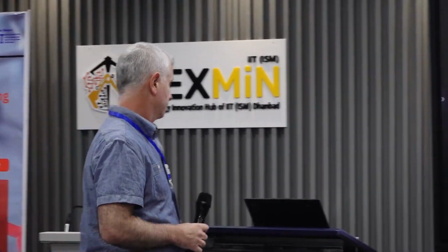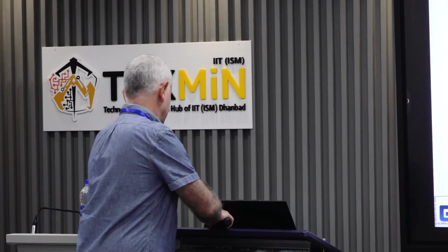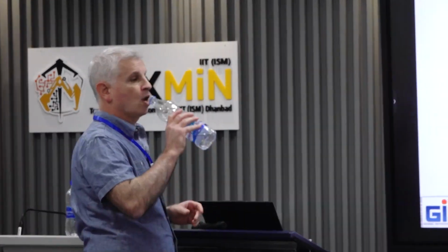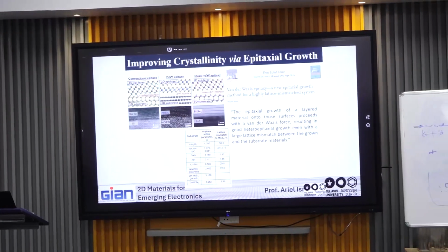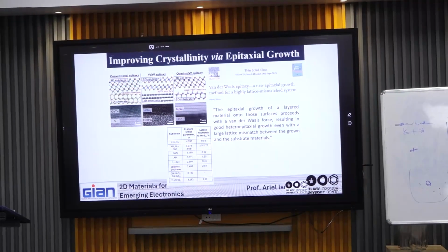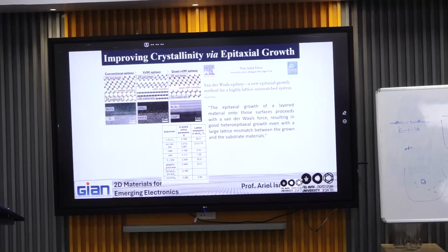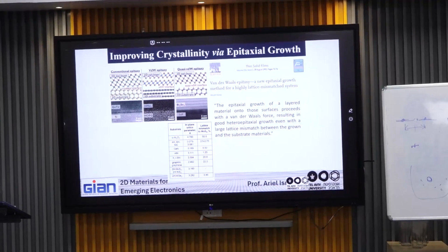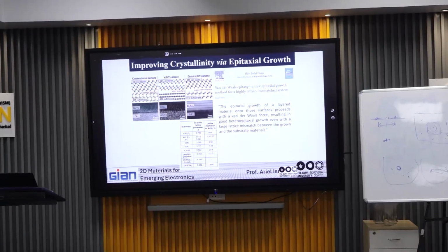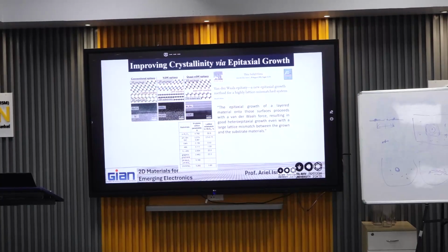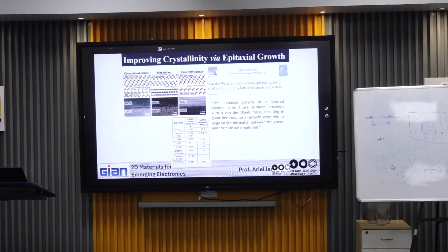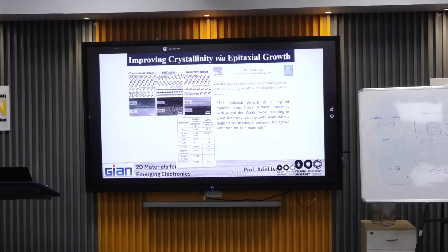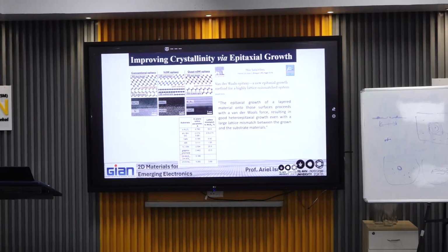Say that we go with the discussing. So basically, if that could be the reason, then let's say we can take two layers, one maybe by exfoliation and another maybe by CVD grown. Usually exfoliated material has fewer defects than the CVD grown material. And then if you grow the second layer over both, and you find that on the CVD layer we can easily grow the second layer rather than on the exfoliated one, then we can grow this.